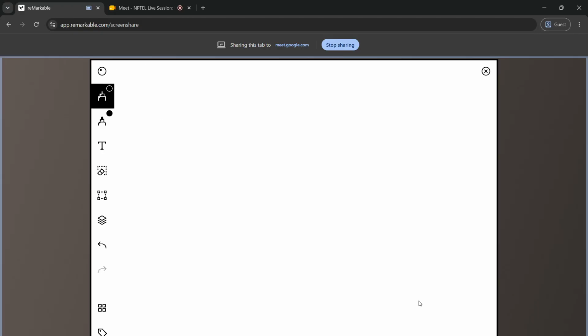That will be straightforward. So we know that the energy integral equation is d dx of integral 0 to delta of u times T minus T infinite dy should be equal to q double prime by rho cp. So we already derived this equation before. Instead of rederiving the equation, the only difference now is previously we had u as a function of y, but now we know that delta T is very much greater than delta, so we can replace this u with u infinite.